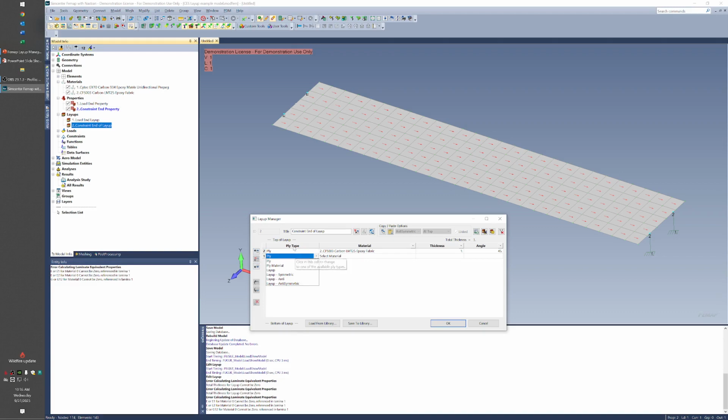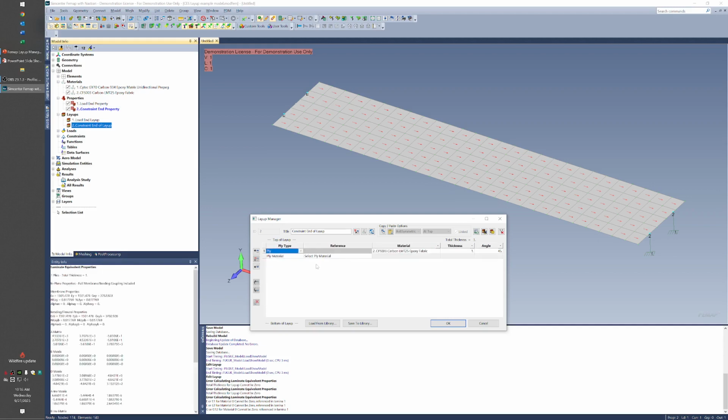There are a few different ways you can define plies. You don't have to necessarily go through and manually input anything. We can go here to the ply material mentioned before, and now we just select this little drop down of already predefined weaves, and there it is. It fills out material and thickness, and we can just change the angle to whatever we want. Let's put in -45, for example.